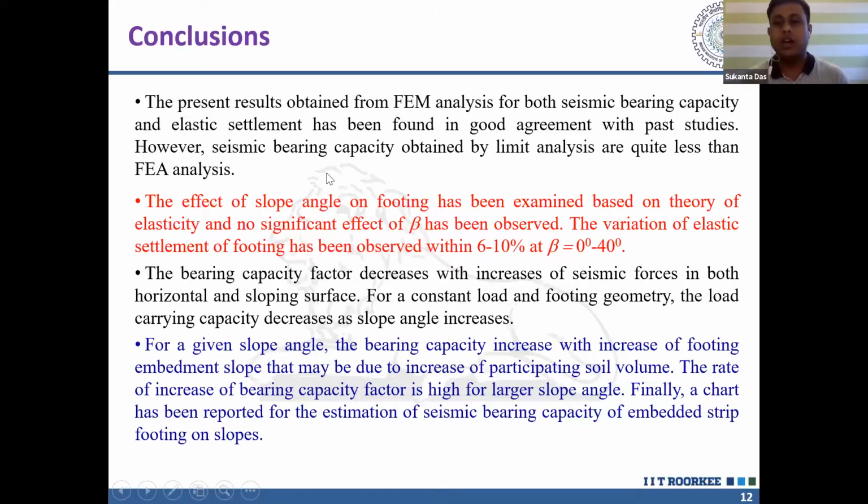From the present seismic bearing capacity and elastic settlement study, the major conclusions are presented in this slide. The present results obtained from the FELA analysis, for both seismic bearing capacity and elastic settlement of the footing on sloping ground, show good agreement with past studies. However, the seismic bearing capacity obtained by limit analysis, whether lower bound, upper bound, or finite element limit analysis, is quite low compared to FEM analysis. The effect of slope angle has been examined using numerical finite element analysis, but no significant effect has been observed.